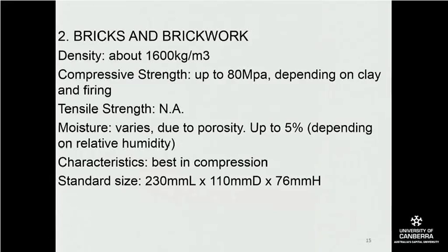The density of brick and brickwork is about 1,600 kilograms per meter cubed, so considerably lighter than stone, but with a very good compressive strength of up to 80 megapascals, depending on the clay and firing. So of course, from that comment, you can tell that bricks are made from clay and need to be cooked or fired in a kiln in order to achieve their ultimate strength.